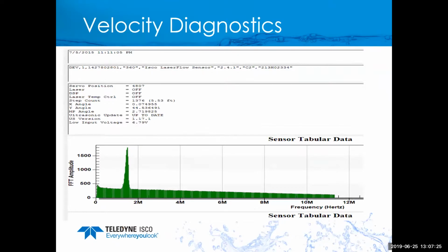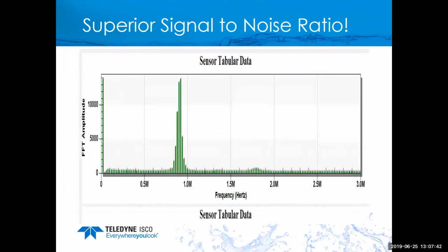Okay, so one of the things that I like about the laser is the diagnostics. I want to know when I get a reading if it's a good reading or not. Every time it takes that reading, the frequency on the bottom is the speed of the water. The more that agree on the return signal, the bigger and better that signal looks. So this signal right here is telling me we have a very good return signal, and we have a lot of agreement on the return frequency. So we're confident in the reading that we're getting.